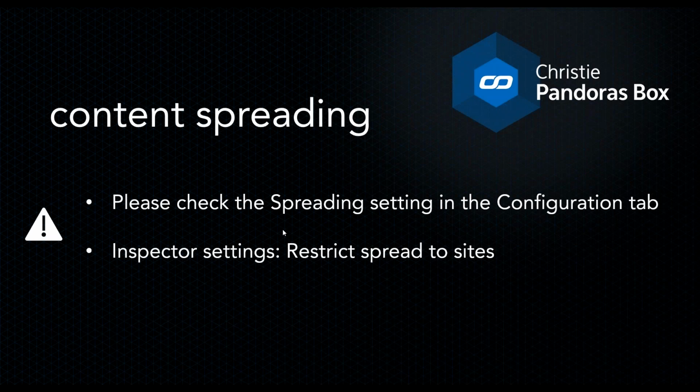And here in my presentation, a warning message. Be careful. Please check the spreading setting in the configuration tab under Global Resources, Inspector Settings, Restrict Spread Sites. Why do you need to be careful? Because of the storage capacity. Imagine you have huge image sequences in a huge resolution.